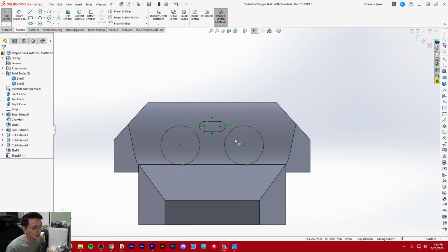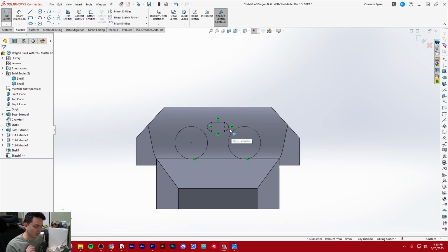So a generic rule is that if you want something to be press fit, which basically just means it fits like a glove, super tight into something, then my rule is I use 0.25 millimeters to have that sort of fit. If you want two parts that are moving and sliding along each other, and there's even more space for them to be sliding, I go to 0.5 millimeters of gap.